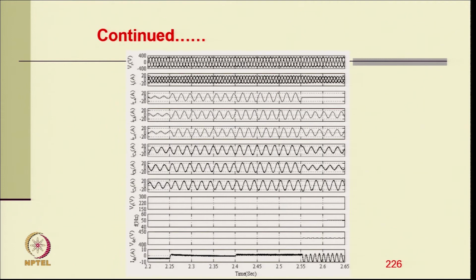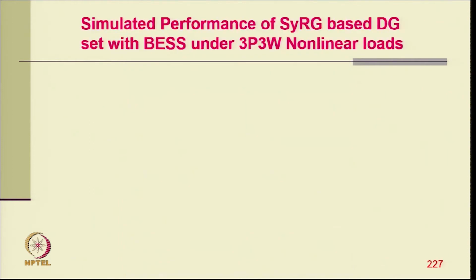And this is the case where we are having a battery operated system. Here we are putting the optimum utilization of the generator from 80 to 100%, and there is a small load, so the battery gets charged. When load is increased the battery is not getting charged, floating between 80 to 100%, and when you have an unbalanced load, the battery gets charged, but with the second harmonic in the battery because of load unbalancing. It regulates the voltage, it provides the power leveling, it eliminates the negative sequence current as well as it supplies the reactive power of the load.